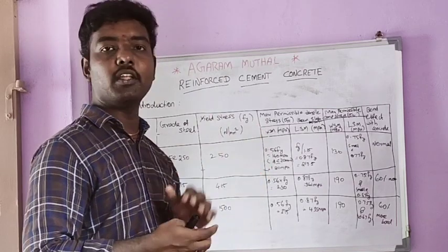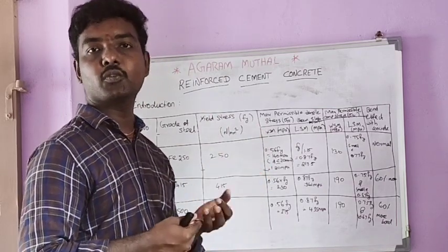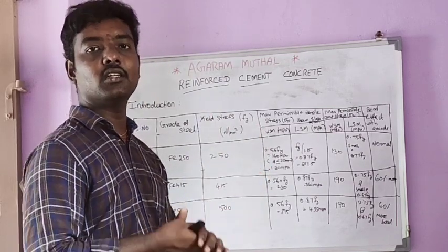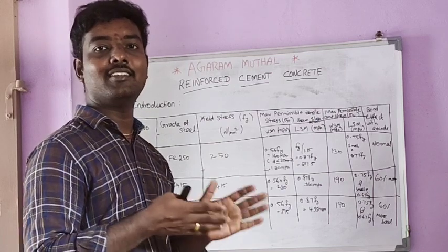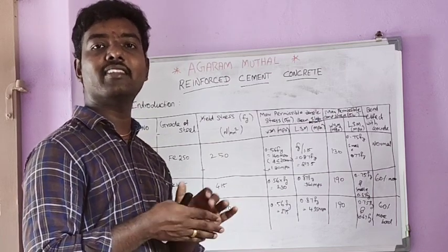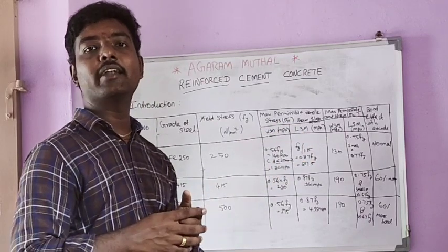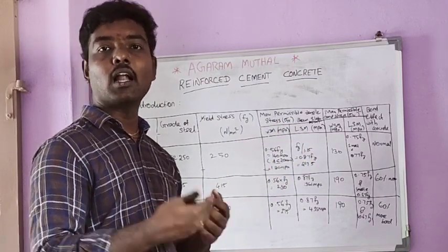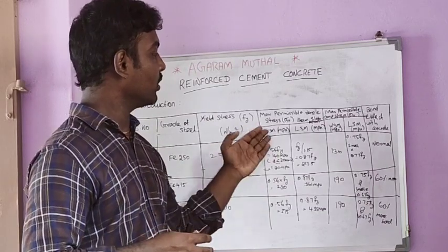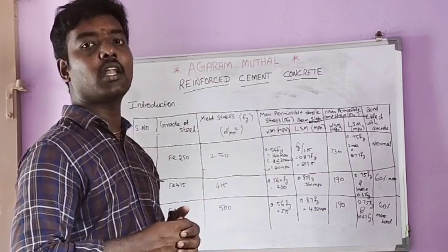What is WSM? It is nothing but the working stress method. This method uses only design loads, which are nothing but safe loads. And in the limit state method, the load is taken as the collapse load or ultimate load. So we consider both WSM and LSM methods.